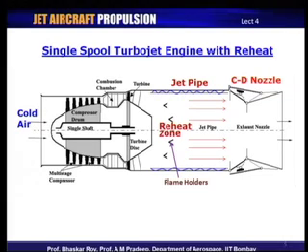So, the liners essentially contain inside them the hot gases coming from the turbine and create a small safety zone for the outer shell of the jet pipe from the very high temperature being created inside the reheat zone, where, as I mentioned, temperatures could indeed be higher than earlier. As a result, these liners are an integral part of reheat or afterburning engines, essentially for protection of the jet engine body.